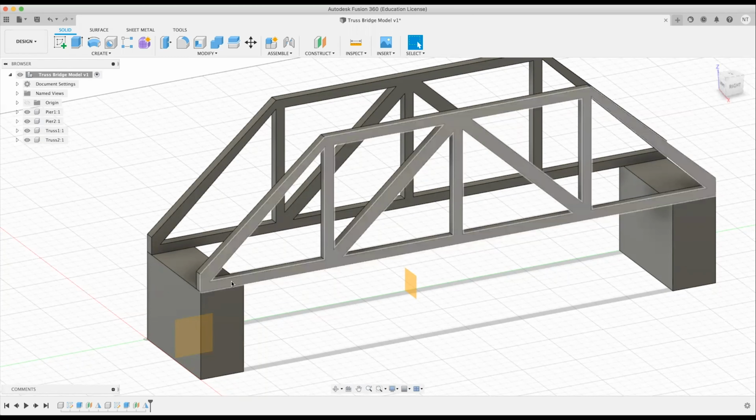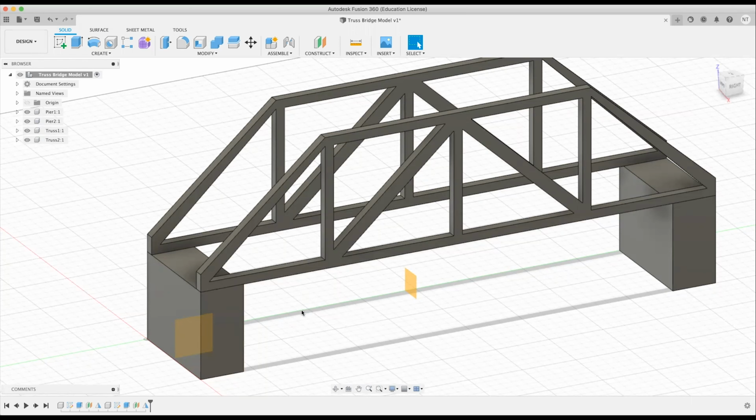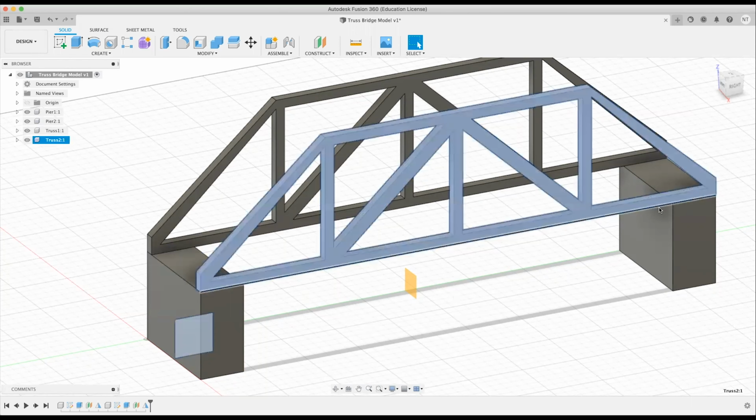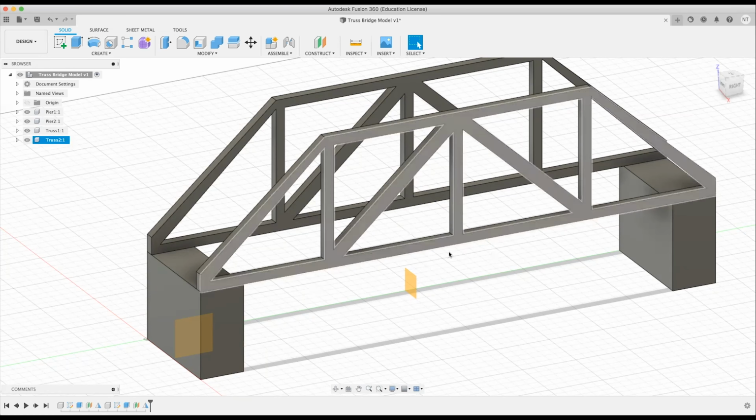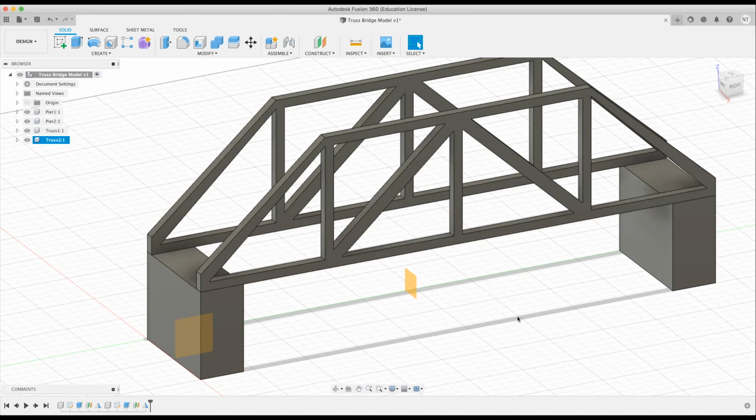And just like we mentioned in the presentation, we have what are called superstructure, substructure, and foundation. These abutments and piers and pier caps are all part of your substructure, whereas your truss member, your decking, and even the girders are all part of the superstructure. So that's just some quick information that might give you more context of how things actually work. But for the purposes of this demonstration, we're simplifying things, and we're going to throw in a couple beams to transfer the load to the abutments, and also add some additional reinforcement in the middle of the bridge. However, you're always free to design bridges however you want, as long as they're safe.